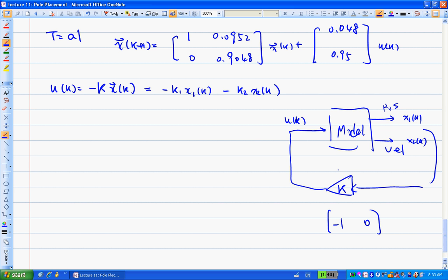So if you design a regulator, what happens is you can twist that motor a little bit, give it an initial disturbance, and let it go, right? If there's control in effect, you'll see that it basically will bring it back to the original position, 0, right? That's basically how the regulator works. That makes sense? So if this initial x1 of k is 0, then you twist it, you give a certain degrees, it'll go back to 0, right? Actually, it will approach 0.